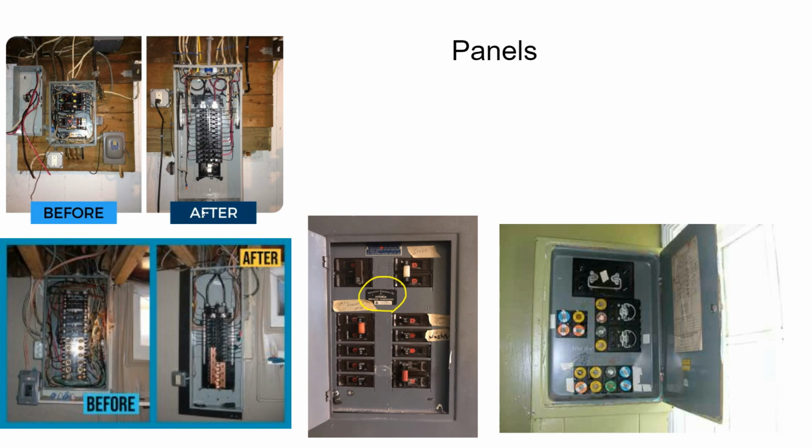They should be not like this. Everyone has seen a house like this. Whether or not you're familiar with it, everyone has seen these messy panels, and that's not good, because what happens is it's hard to work on. You want to add something, you got to move a bunch of stuff. Not only if you want to add something, but if something goes wrong, it's harder to trace out. If it's neat, it's easier to work with. So you don't have all this messy stuff up here. You don't have all this.